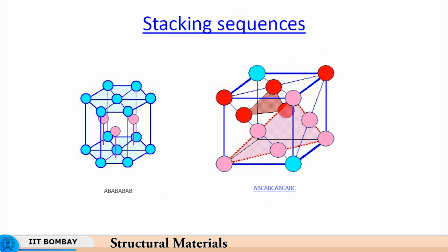Now this stacking fault doesn't directly interfere with the work hardening as such, but depending upon the energy that is needed to create a stacking fault, the possibility of the material undergoing either so-called dynamic recovery or dynamic recrystallization is affected.